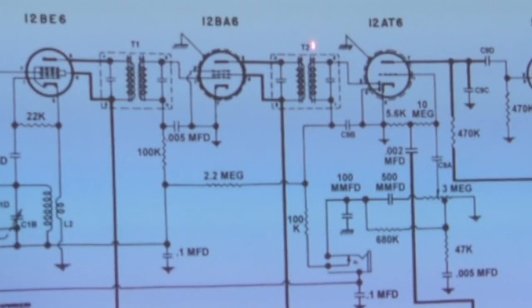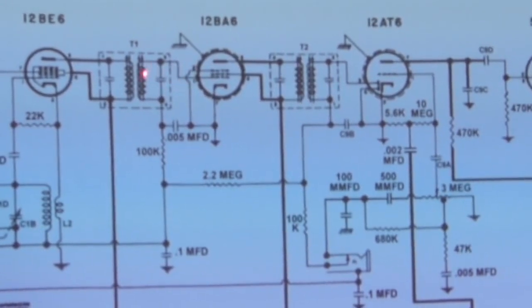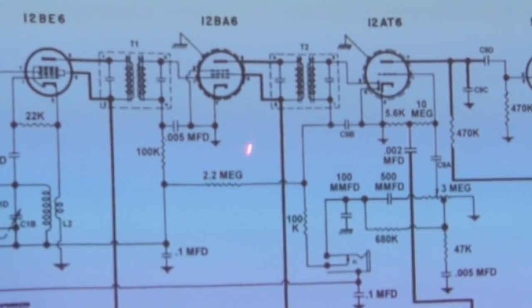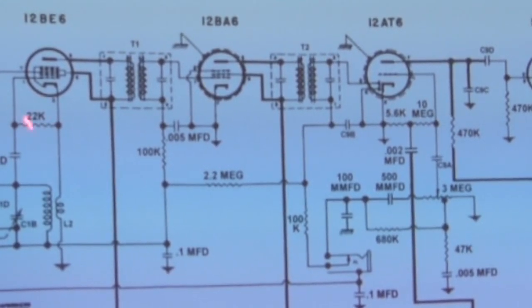Well, okay, I won't drag it out, but you better start looking at the connections in the circuit. Are the values in there correct? Has somebody got in and monkeyed with the value, changed it around? Is there a short somewhere in the circuitry? Even in the socket itself, is there a leakage path or a short path in the socket connections? Those are all possibilities. They're a little more rare, a little more infrequent, but there's something that you have to keep in mind, just in case you need to fall back on that.